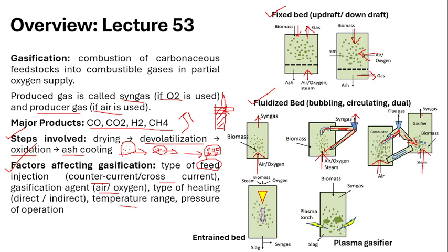So gasification happens. Syngas is collected from the top of the gasifier here, and some of the gas is recycled back into the combustor. So again and again, initial preheating type of combustion is happening here, and whatever gas is produced is helpful for gasification. That is the point here. That is what is happening in the dual fluidized bed reactor.